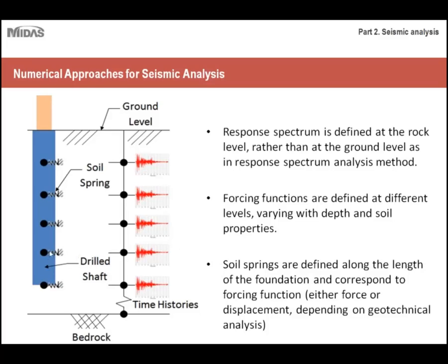The main purpose of these soil springs is essentially just to model the oscillations in your structure, as well as to model your seismic loading functions on them. These loading functions will apply a different seismic loading condition to each of these nodes and each of these springs, and therefore you'd be able to get a much more detailed and accurate analysis.